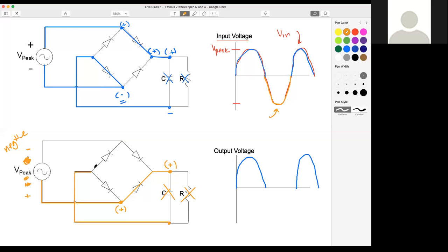Okay, now we have another decision to make. And again, it's easier, let's just work backwards. So let's get to this point. Is this point positive or negative during our negative half cycle of our input voltage? Who can tell me? Negative, exactly. Great. So furthermore, which diode is that going to force to act like a closed circuit? Which diode is that going to forward bias? The one on the left or the one on the right? Omar said up left. Daniel said up left. Yep, exactly, guys. Great. That's going to short, isn't it? And that's going to complete our path. So one of the really cool things is, take a look at this.